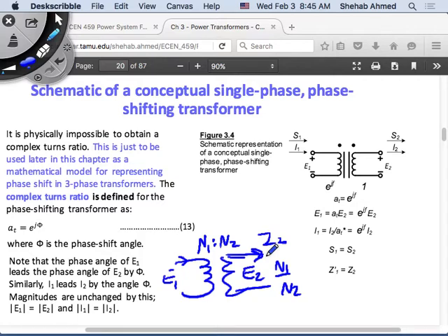It's a magnitude. Is there a phase shift in what's happening? Is there a phase shift between the currents on the primary and the secondary side? No. There is no phase shift in the ideal transformer, as we discussed. Now, this is true when we talk about star-star transformers as well, in 3-phase, or delta-delta transformers, because this phase winding will be in phase with this phase winding.